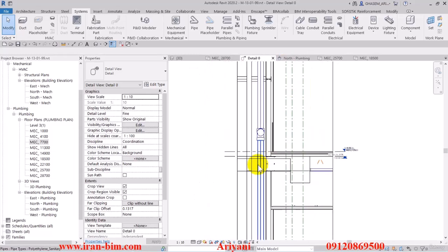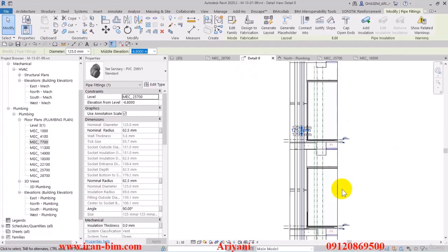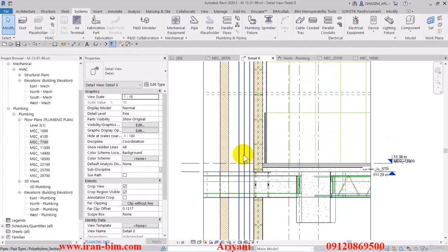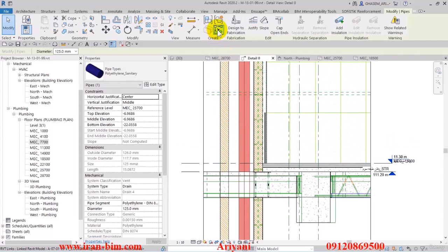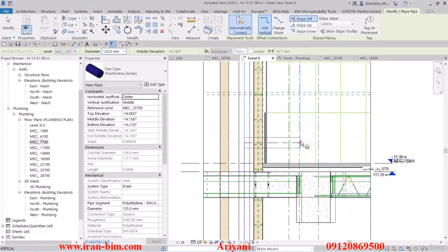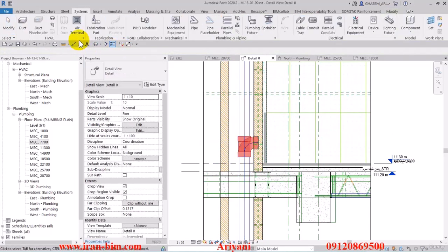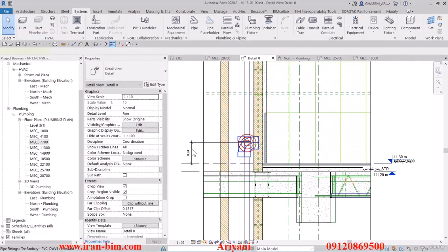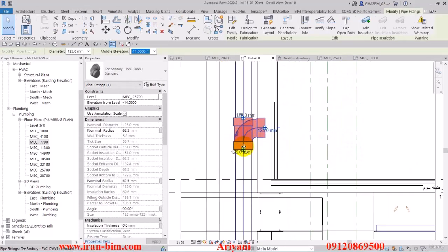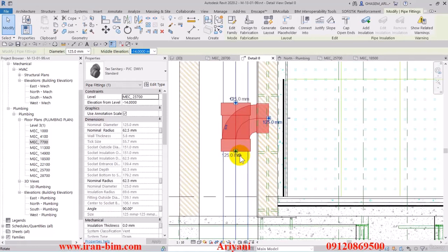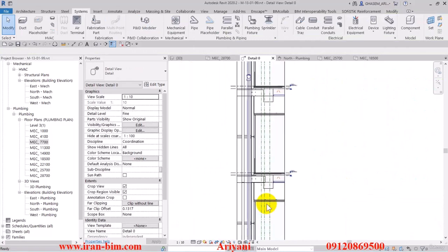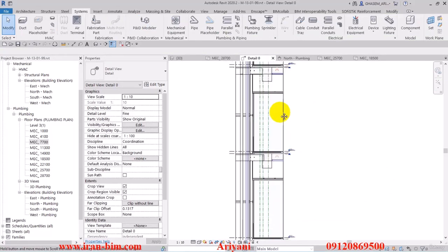So after we've done that, we'll go over to the level that we have here, which is 11.3. And then here we'll draw a horizontal piping and then delete the pipe piece and keep the fitting. Now I'll select the align tool once again and measure from the level to the center of this. Alright, so edit it to 0.4. After that, I'll delete the measurement tool itself, and then using this arrow that we have here, I'll rotate this towards myself, and there we go.